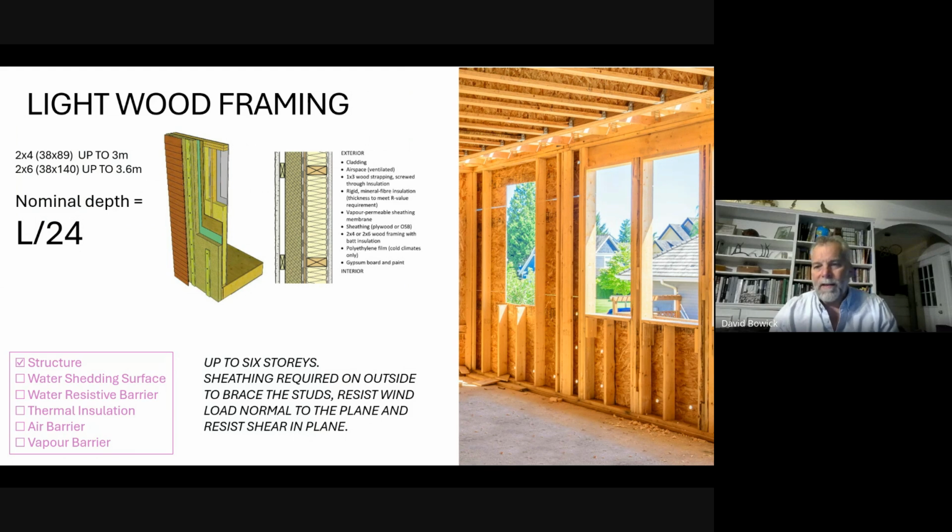But when this became the default, we weren't looking at cold bridging, so we weren't looking at the holistic performance of the wall. We were looking just at the performance of the insulation within the cavity without acknowledging all the other flanking thermal heat loss paths. Now we can't do that. We have to prevent thermal bridging. We can't simply insulate our cavity. That's not an acceptable wall anymore.